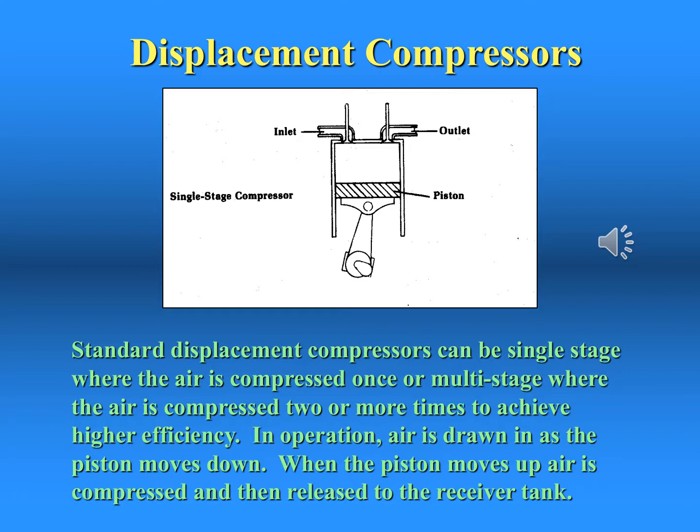As the air is compressed, it gets hot because energy was required to compress it. This energy is transformed into heat and is not usable for doing work. In the pneumatic system, the greatest amount of heat and wasted energy occurs at the compressor. To make matters worse, when the heated air gets to the receiver tank, it loses temperature and pressure and aggravates the already poor efficiency of the system.